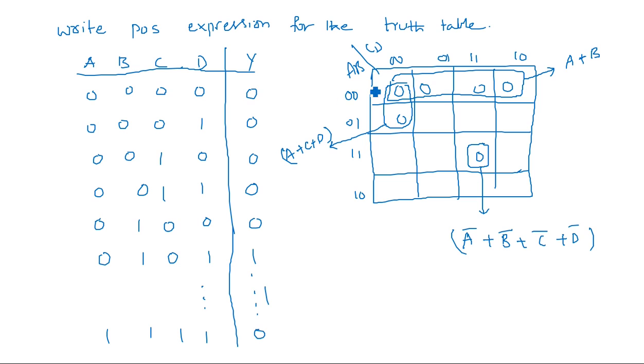Okay, we have to remember one thing here. When you are mapping, see, three different combinations are there. One single zero combination is there, two zeros combination is there, four zeros combination is there. Okay, single zero gives all four variables. There is no elimination. Once again I am repeating, single zero gives all four variables without any elimination.